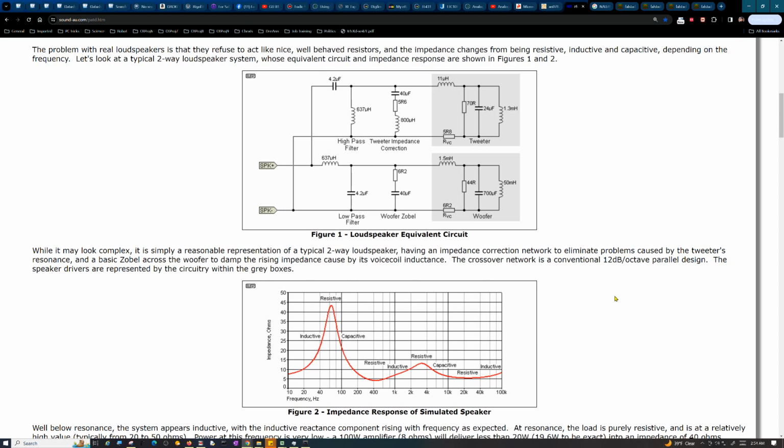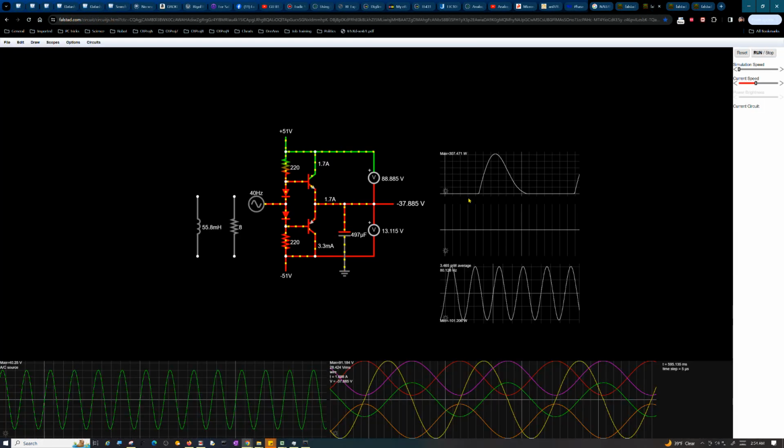That's why with most bipolar transistors, the only way you can actually get any real current through them is under 30 volts. So just make sure they never have 30 volts across them with 1 amp of current. But this article shows you that there are some caveats to that too, because of when peak current may occur versus your peak power. So it's not necessarily simple if you've got a reactive load.